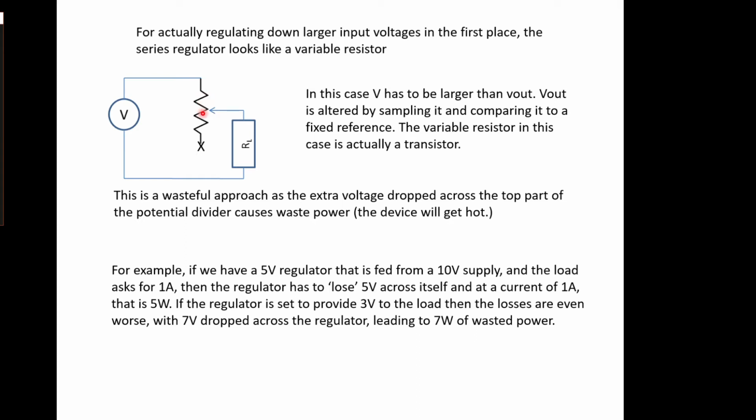It's also very inefficient, and in the modern world we like to be efficient if we can. So linear regulators don't tend to be terribly efficient. They're not bad if you can drop this voltage right down to be close. So if you wanted a 5-volt regulator, if you could make sure that this was close to 5, so between 5 and 6, then actually they're not too bad. But it's quite difficult to design linear regulators that have a very small amount of headroom there. But anyway, they're very low noise, which is nice. So you get a very smooth power supply here, at the consequence of a little bit of waste.